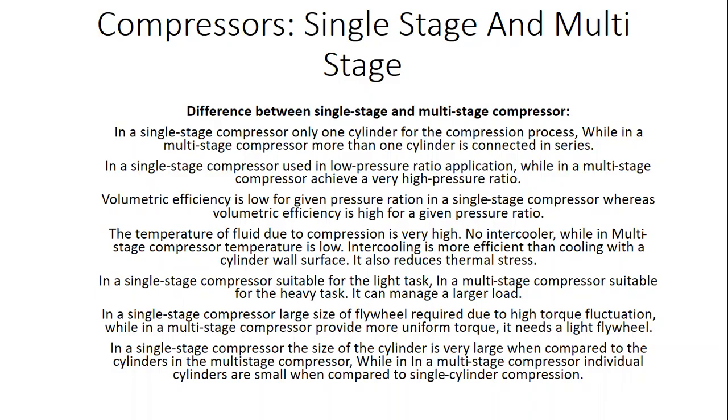A single stage compressor is used in low pressure ratio applications, but in a multi-stage there is a very high pressure ratio. Of course, the ratio of the air taken in to the air taken out in a single stage is very low, but in a multi-stage, the ratio is very high because there are a lot of processes involved there. The volumetric efficiency for a single stage is very low, but for a multi-stage it is very high.